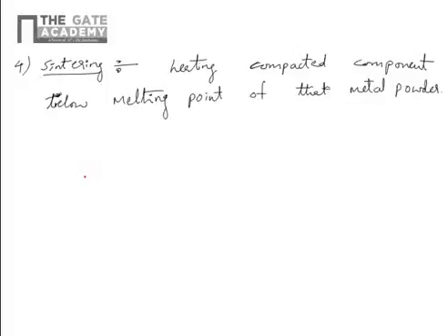The final component you get is the powder metallurgical component. Then you may do some heat treatment, depending upon the application, if you want to remove any stresses developed.